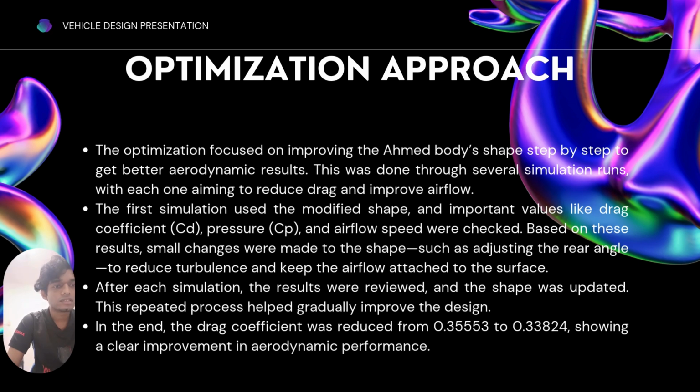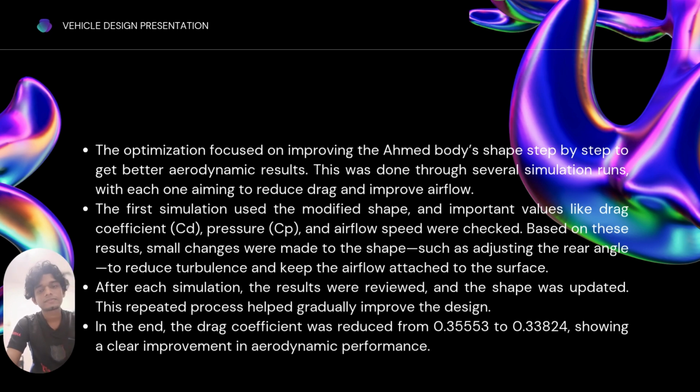After each simulation, the results were reviewed and the shape was updated. This repeated process helped gradually improve the design. In the end, the drag coefficient was reduced from 0.35553 to 0.33824, showing a clear improvement in aerodynamic performance.